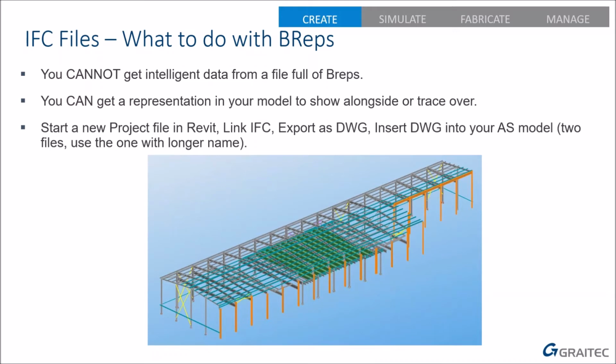So all those three techniques will allow you to get a picture of the IFC in your Advanced Steel. That looks great. None of those are steel beams. That is an Advanced Steel screenshot, but none of them are intelligent beams. They're just 3D solids. But you can snap to ends, you can put your steel work next to them and so on. So it depends what you need it for. It's better than nothing, which is the alternative.